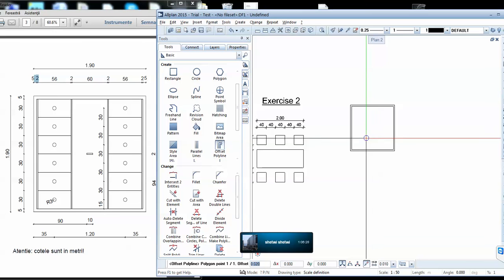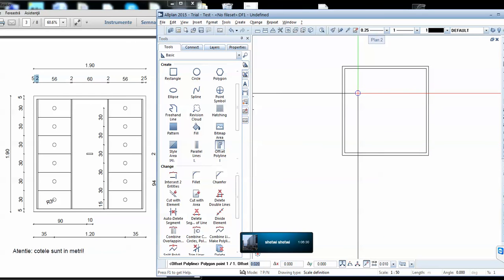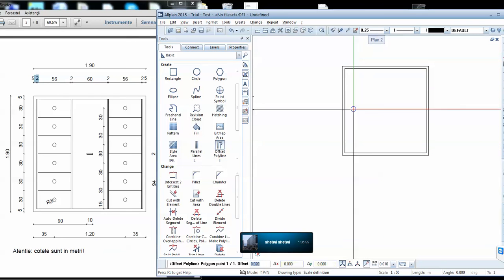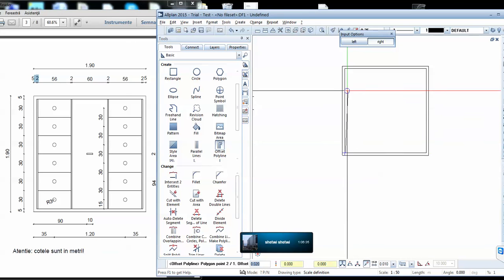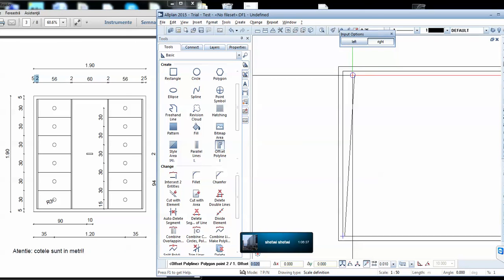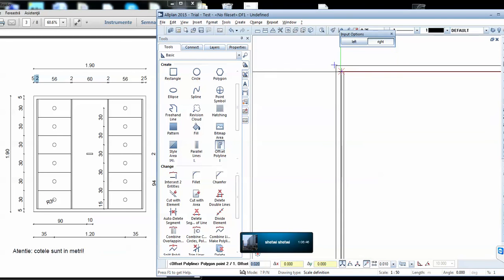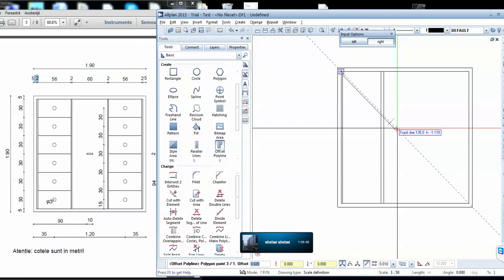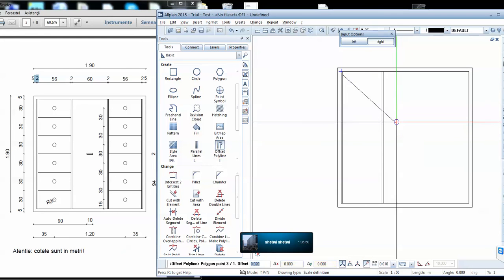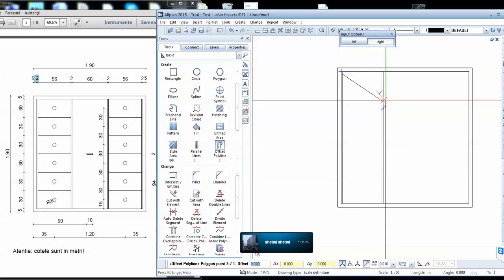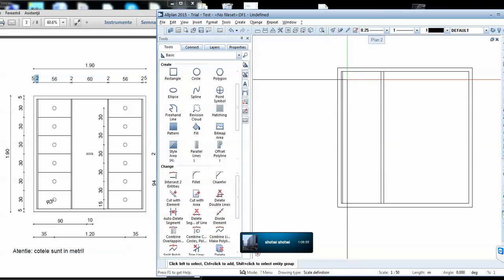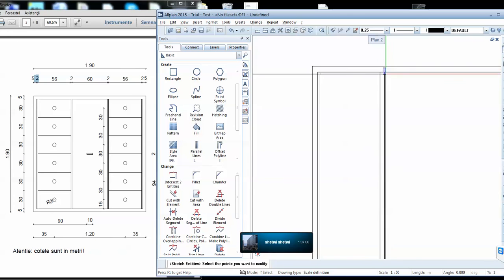And then I'm going to draw this line. It doesn't matter if I start from above or under, because I can correct myself. If I start from downward, I see here right and left, because I can offset on the right side and on the left side all these polylines I've defined before. So if I go here, I don't like the last distance. It seems it didn't work out. It offsetted more distances.